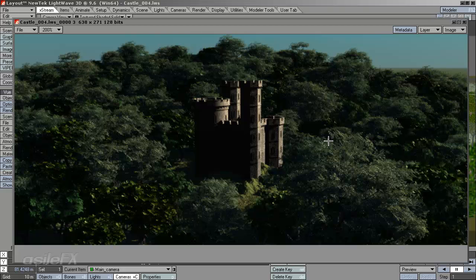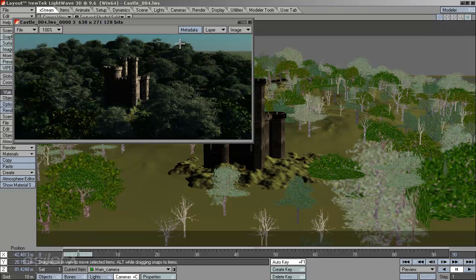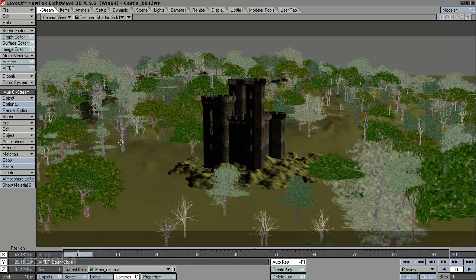And for stills, it's not going to be something that's really necessary. You can just have a higher anti-aliasing. Really depending. The balance between the two, you really have to kind of play around with depending on the scene. Sometimes it's better, instead of using a high anti-aliasing amount, just to turn on the texture filtering. The main thing you need to be careful of when you're using texture filtering is primarily with plants. If you have a high amount of wind moving around the objects, the blur is sometimes so intense that the trees lose all their leaves.